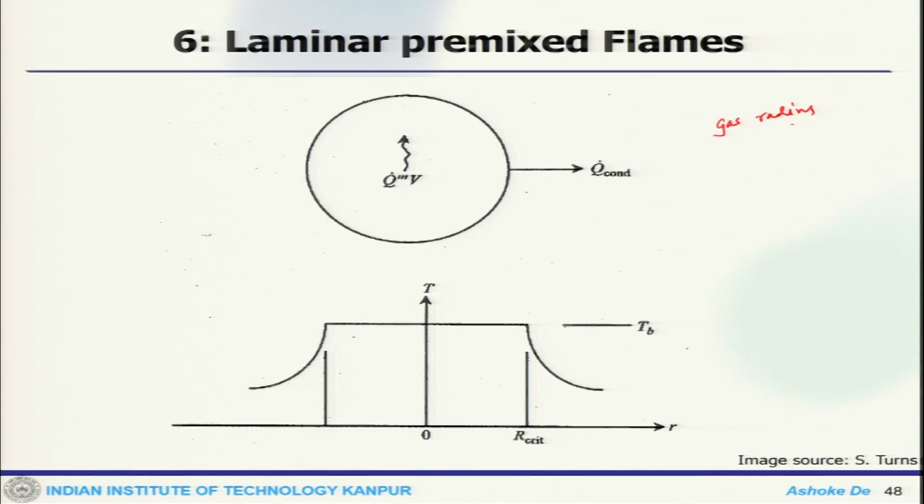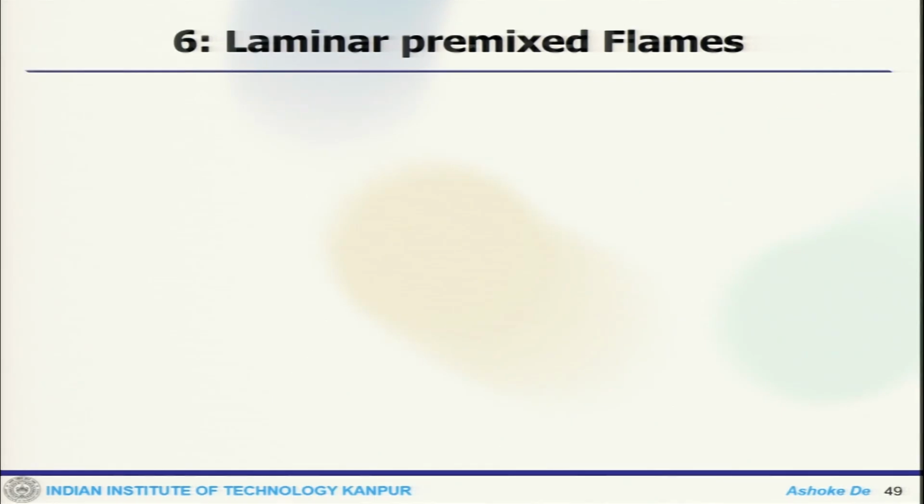and here we will put the spark, and this is the critical radius, and that would be the burn temperature because of the heat production. So, we can correlate the heat generation from the energy equation to the heat conduction. That means we are equating the heat generated due to reaction and the rate of heat loss to the cold gas by conduction. So, these are the equations that you get. Basically, it is a total amount of energy.